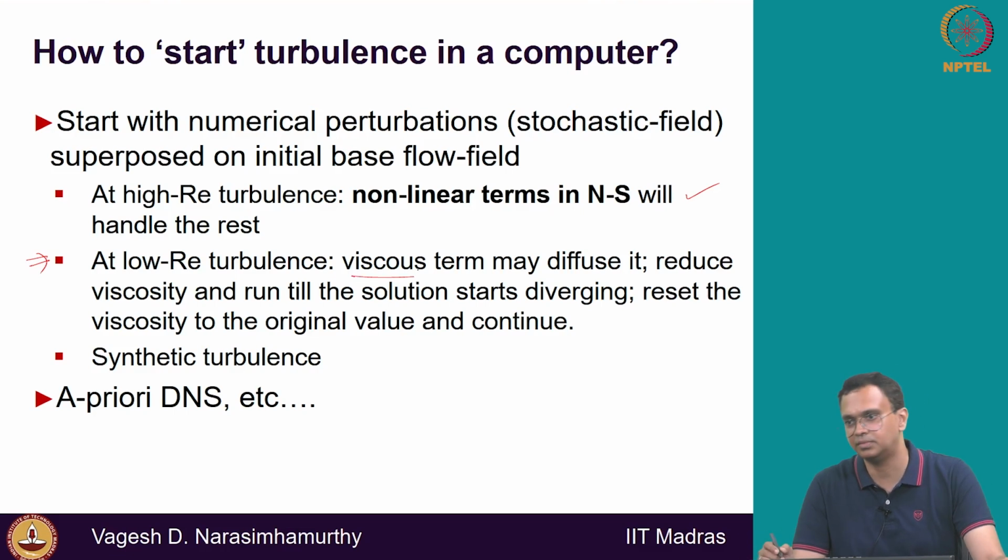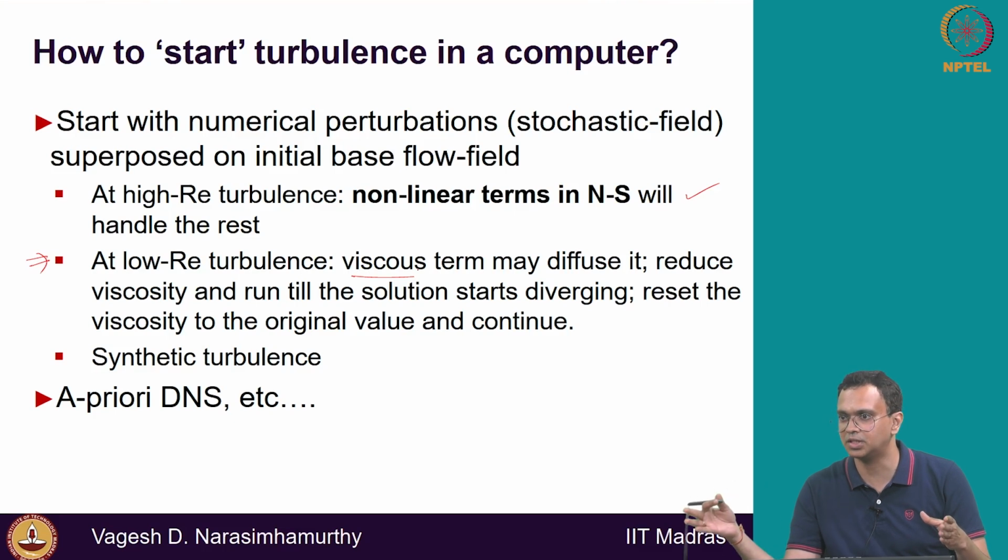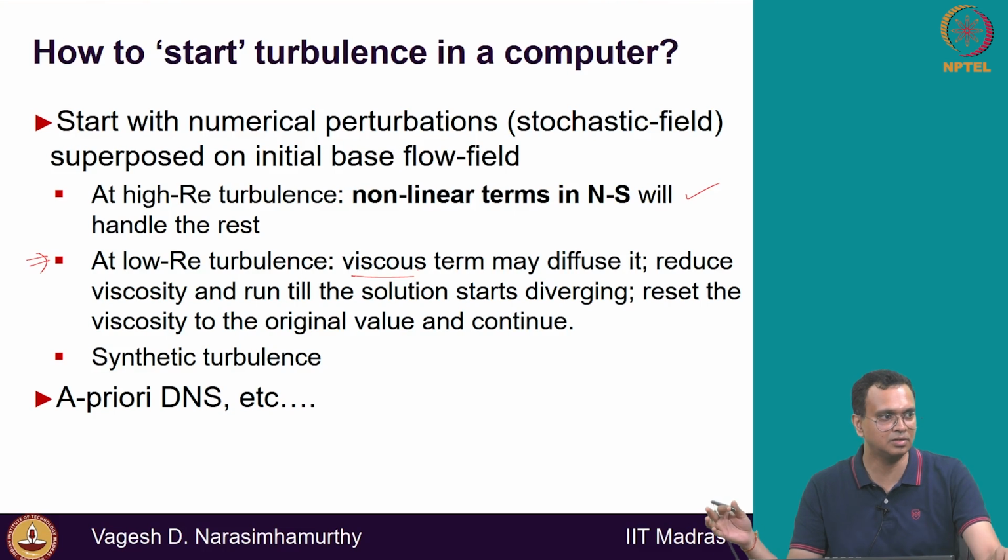Okay, you are running it in time. You run for several time steps and then we see that the flow looks like laminar flow. You give a very random flow field looking like turbulent, and you run your Navier-Stokes simulation for some time steps, and you see that it looks like laminar because viscosity is killing all the perturbations. You are getting a converged solution but not the correct one.